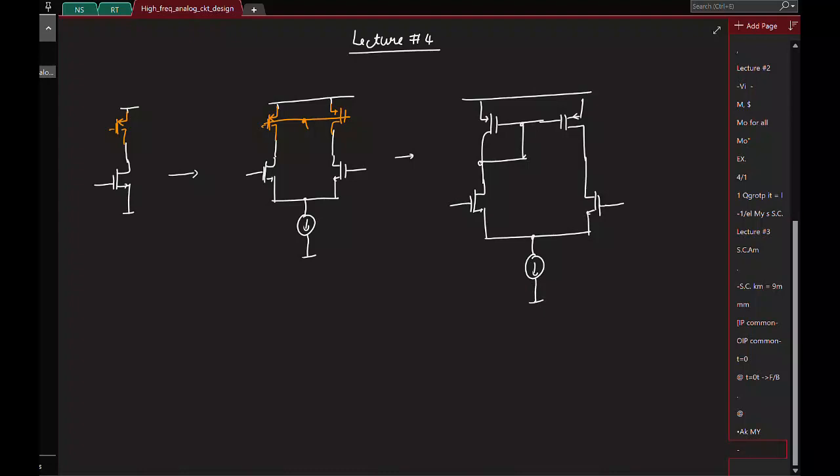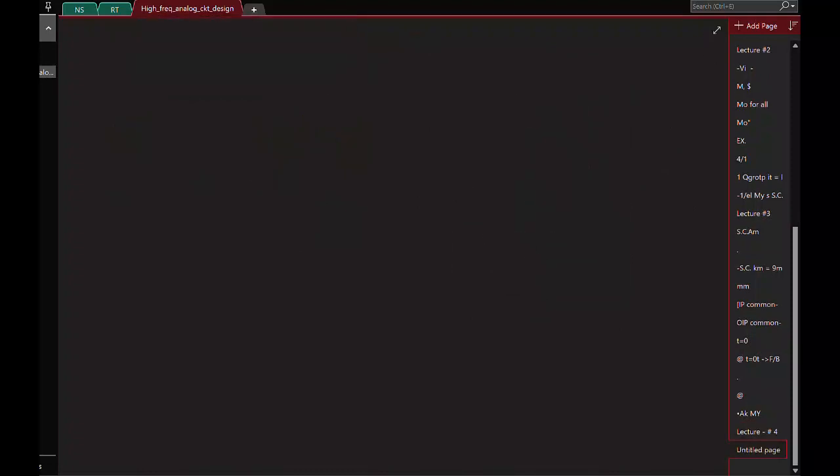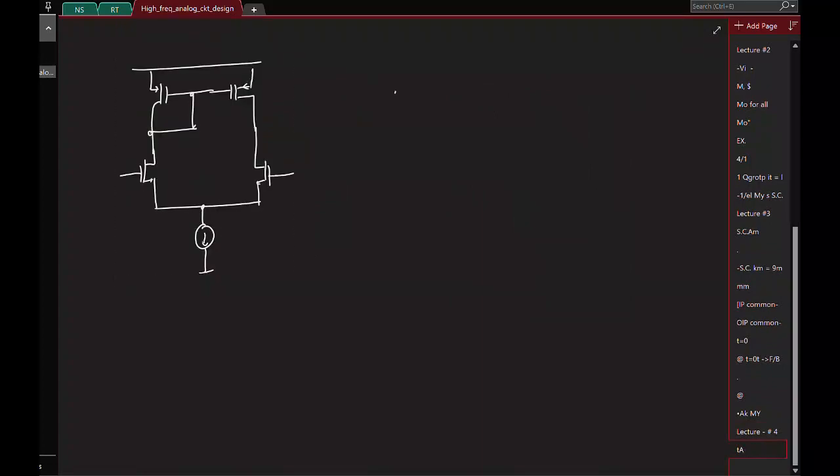Right, and we also looked at the small signal gain of this, and being an asymmetrical circuit, we calculated the gain using the short circuit GM times the output resistance. Of course, in your assignment, I will ask you to derive why this makes sense, and you'll know what the assumptions behind this are, or whether it is valid all the time. If I label these transistors this way, what is the short circuit GM here? GM was GM1, and what was R out? It was the parallel combination of the NMOS and the PMOS R outs.